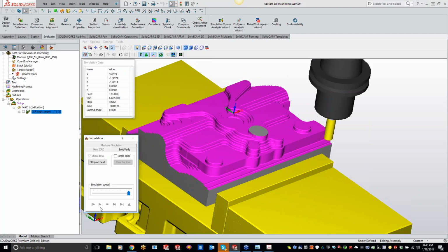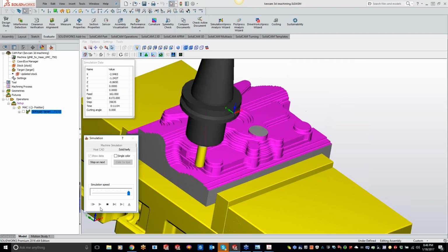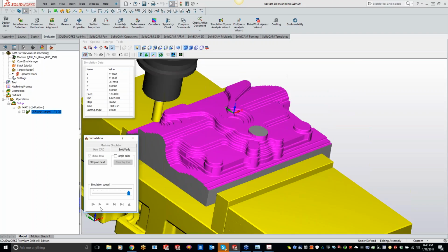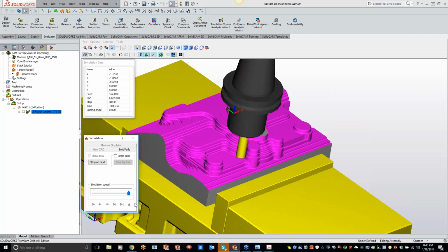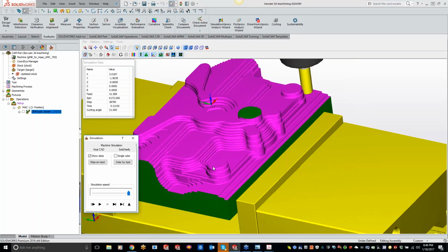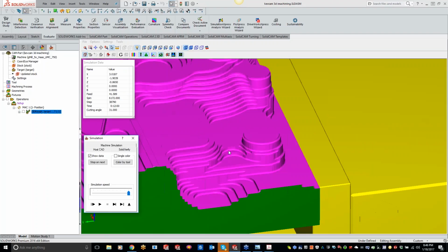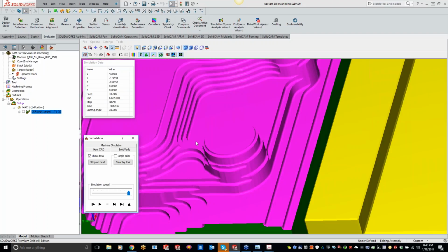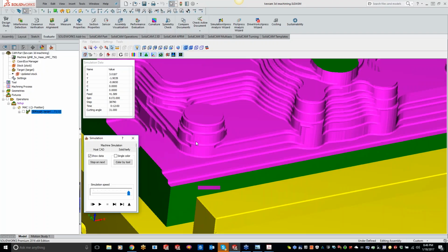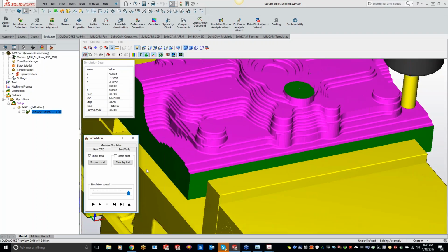Well, with iMachining, what it does is it accommodates for all that, and it's going to automatically slow down, like Brendan was saying, and it's going to change the approach angle of it. So, like right there, as we're getting through, and we might not even actually machine through here because our end mill might be a little too large, but right here we have a thin wall. It's automatically going to switch around the feed rate for you guys and approach it with a different angle of engagement, so we're not having that little piece or that little slug curling back behind itself, and then when we come to take that second cut through there, it's getting rammed into the end mill.